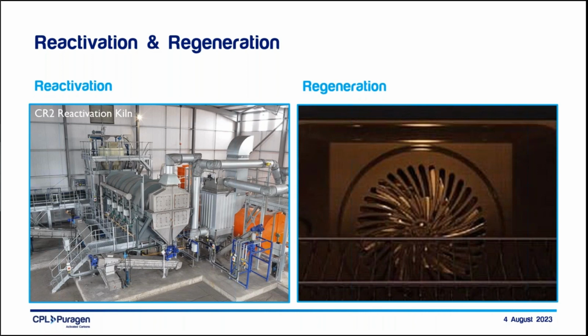Then pyrolysis and carbonization of non-volatile organics taking place up to 700 Celsius. And then the last step is gasification, taking place above 800 Celsius in an inert atmosphere using an activating agent to remove carbonized material which was formed in the previous pyrolysis step.